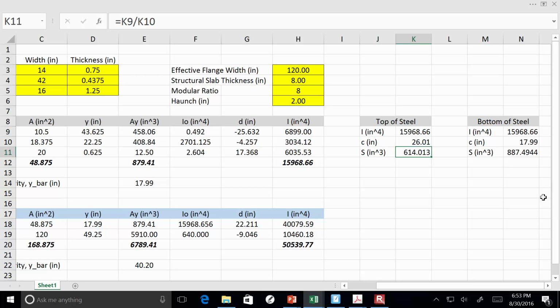All right. Make sense? And just divide those two out. So what that means from a behavioral standpoint is, looking at these section moduli, I can make some pretty straightforward assessments. Section moduli are in a way an assessment of the performance of a given section. If I'm looking at these two section moduli, the section modulus for the bottom flange is larger. That means in turn, when I apply moments, it's going to have smaller stresses than the top flange. See what I mean? That's kind of important.